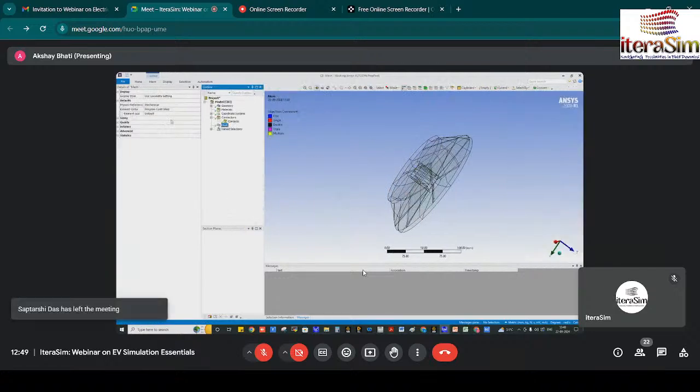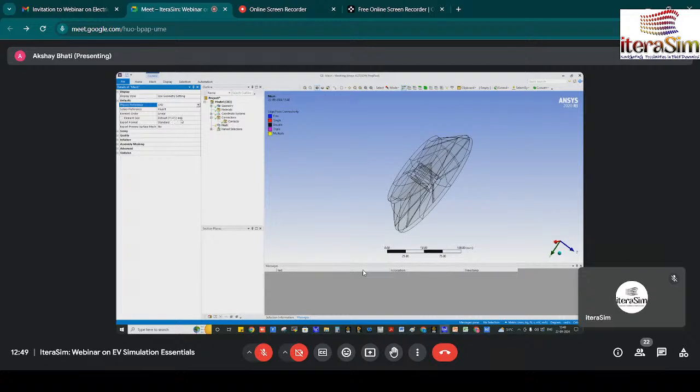Okay, after that we will mesh. First we will take that CFD meshing in Fluent, that will automatically come. And mostly for turbo machinery you can take the maximum element size as 4.5. Mostly 4.5 maximum size we can take. And in sizing, we need to capture curvature and proximity.